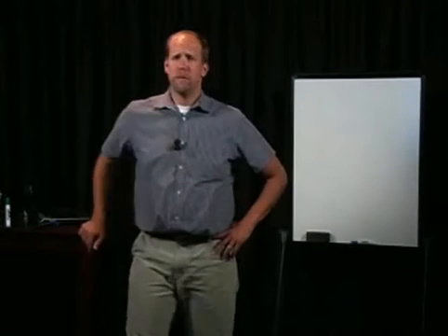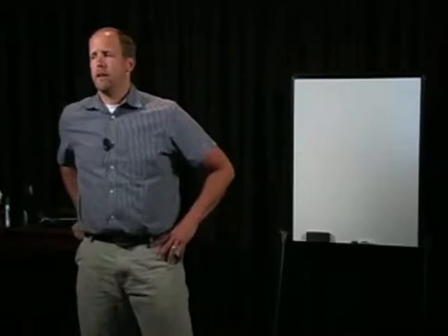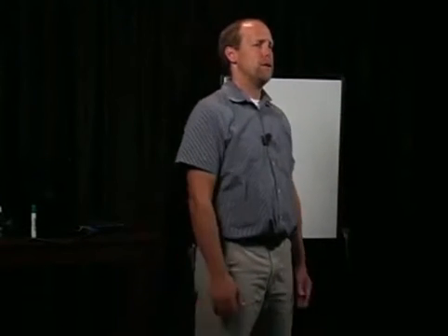A digital picture should be taken of all the areas of concern: moisture intrusion, water damage, musty odors, apparent mold growth, conditions conducive to mold growth, and any other system or component of the building that may be having problems and contributing to moisture or mold growth.